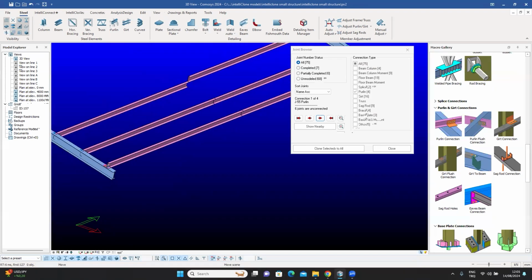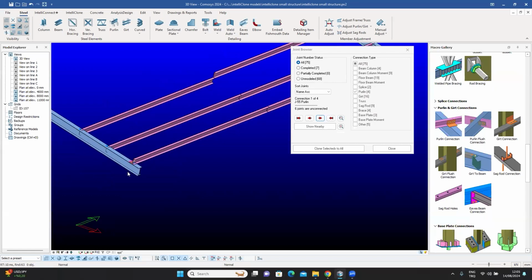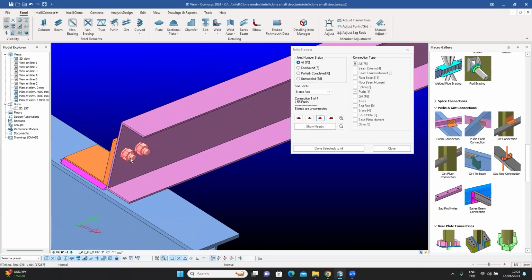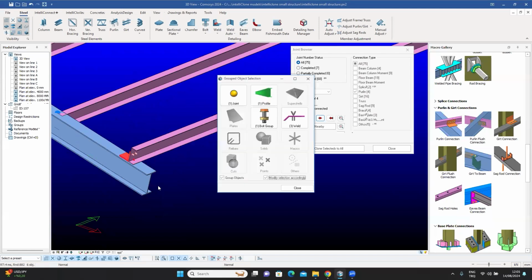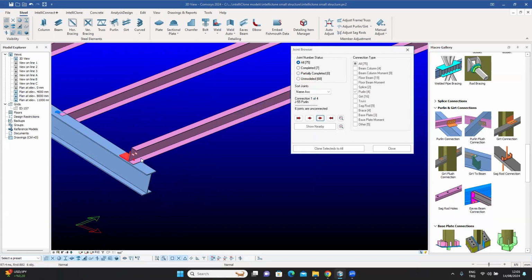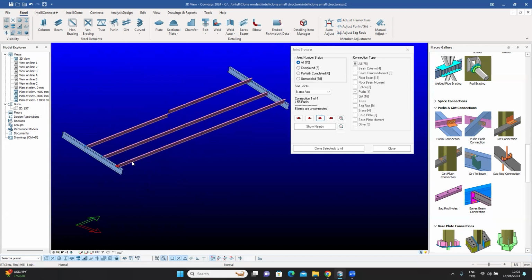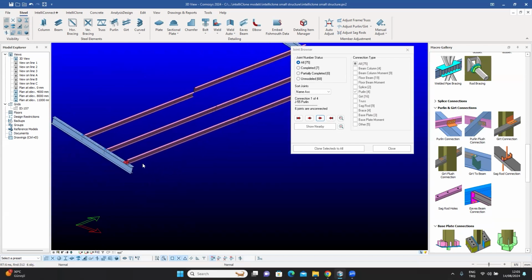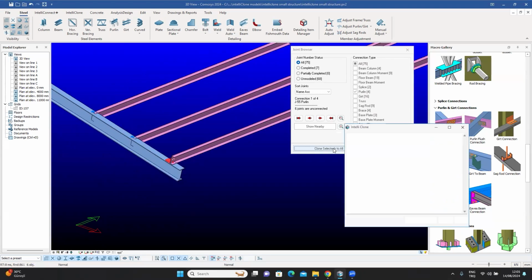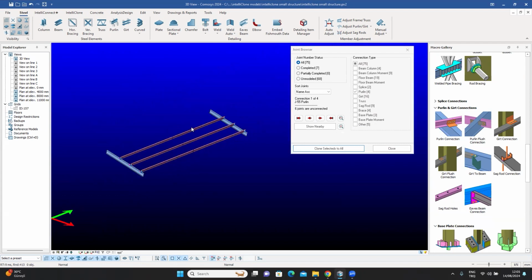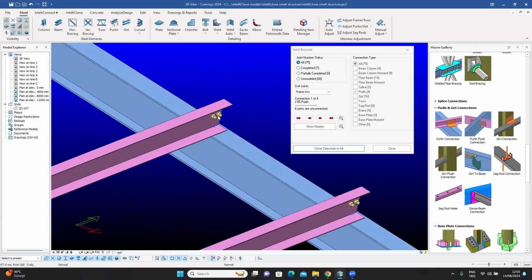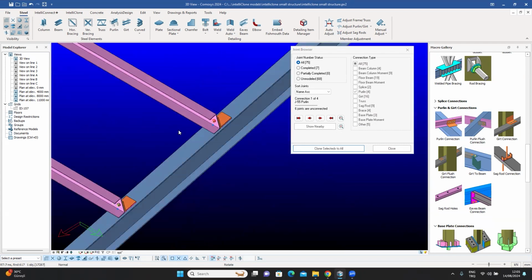They've got all sorts of offset errors in them, but I'm not concerned with that. I'm just going to select this, rather something like this, making sure I have one joint and the rest is from the macro. And if you see on the screen, if I zoom in like that, press clone and press proceed, immediately everything else is adjusted according to the source. The offsets are adjusted on the other side as well, and I have my connection exactly the way I want.